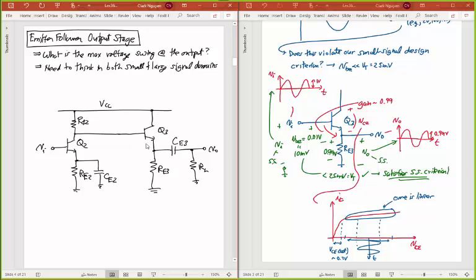And that's the nice thing about emitter followers. They have a low impedance, so they can drive low impedances here. And probably more importantly, they can deliver the current needed to drive that impedance. The current's going straight from VCC here and out into RL in this case. Actually out into both R3 and RL, since that looks like a short in the small signal sense.